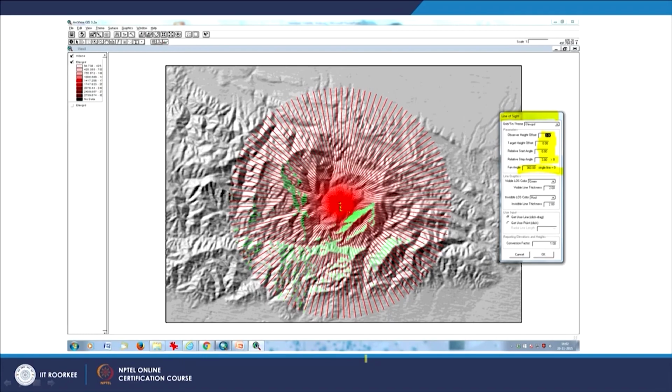If you recall the definition of GIS, at the end it says that it allows us to do modeling. Modeling means prediction, and prediction means nothing is happening on the ground. We are trying to model it, predicting how it will happen, how it will look, and that way GIS, and especially this technique of view shed analysis, is a really very powerful technique, by which we can exactly know, once this building comes or this tower comes, how much area would be visible from the top of that building or middle or wherever you want to analyze.